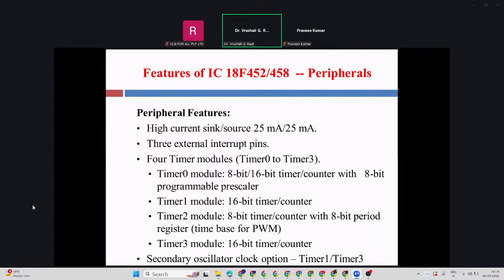You very well know that a timer is for setting the delay. What is a counter for? For measuring the external event, the counter is there. Is it right? A timer is using the internal clock frequency. What is a counter doing? The clock is the external event which is coming to the counter. That is acting as a clock for the counter. That is the difference, right?